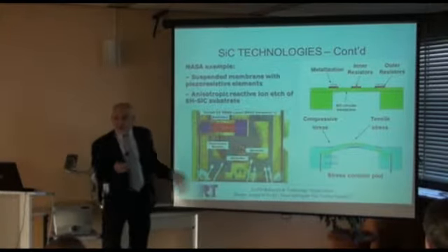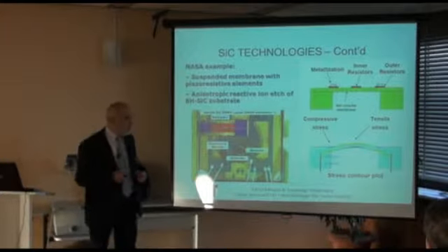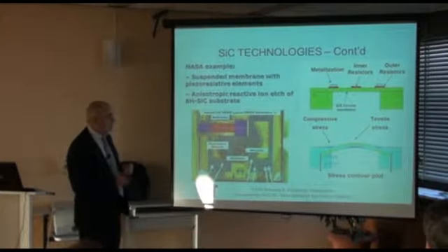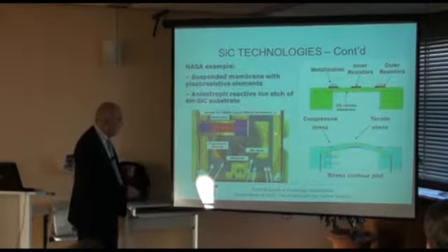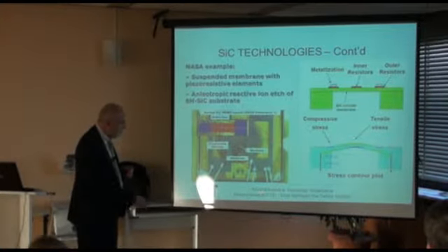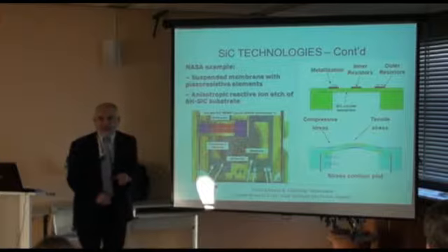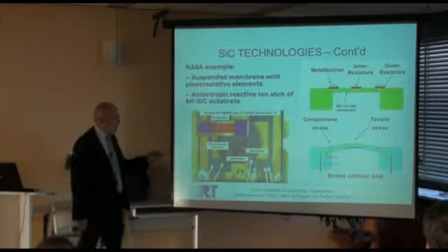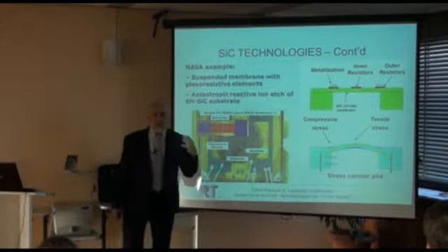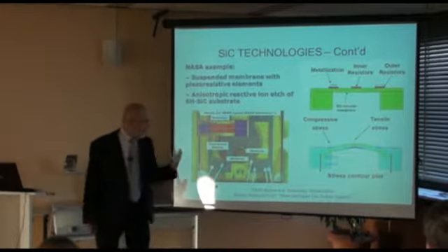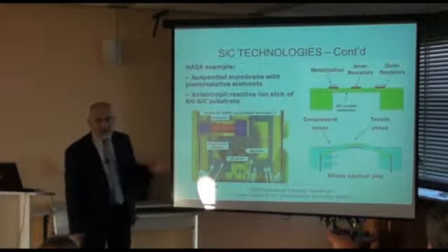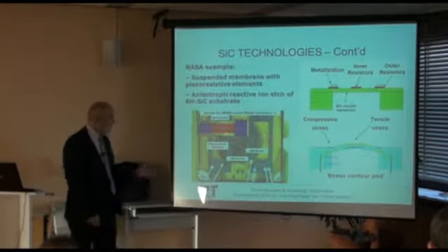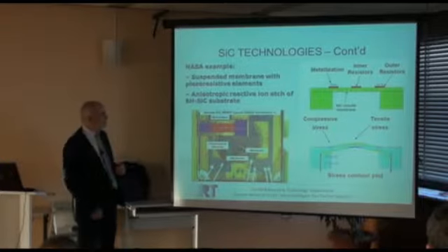Metallizations are the weakest point in here, as I have mentioned. The electronic circuit is built on the side. Here is the membrane side. Wires would lead to the electronic circuit down here. Usually what the electronic circuit includes is basically a converter from the resistance to current, eventually analog to digital, and we have a digital output.